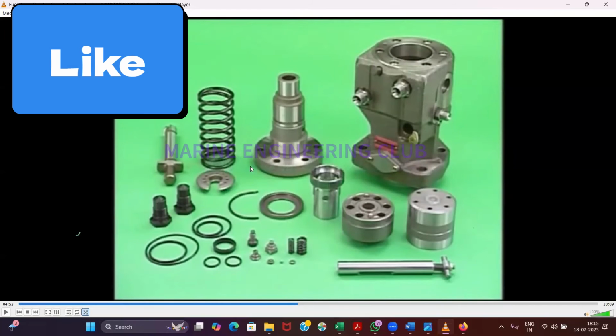O-rings we have to replace every time. Plunger and barrel are replaced as per your running hours and as per your leak off. In a running engine, if I remove the leak off line, it is fitted here. Can you see my cursor? Yes, sir. In a running engine also I can remove it to check if there is any leak off or not. Normally what I do is run the engine in offload condition and remove the leak off line. If too much oil is coming, that means I have to replace my plunger and barrel. Agreed?